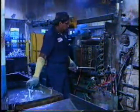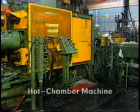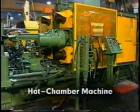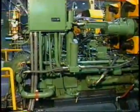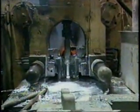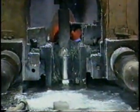The two principal types of die casting machines are the hot chamber machine and the cold chamber machine. The hot chamber machine is used mainly for die casting zinc and other metals of low melting temperature. However, it is also used to die cast magnesium. The machine's shot end has a holding pot, which is a reservoir for the molten metal, and an injection system for transferring the metal to the die.